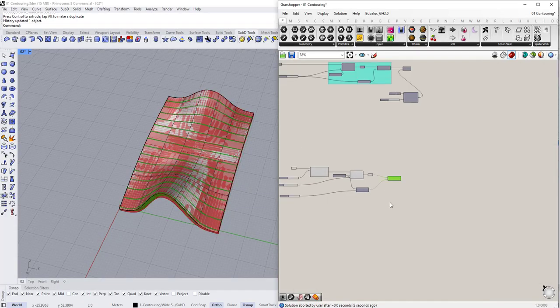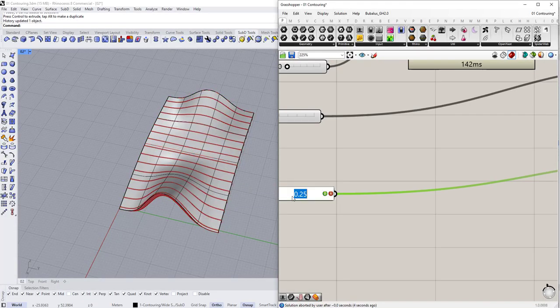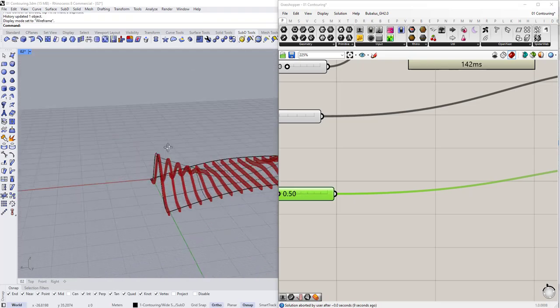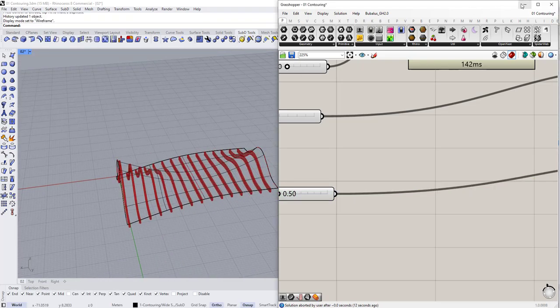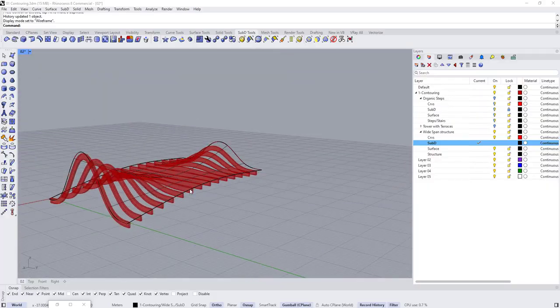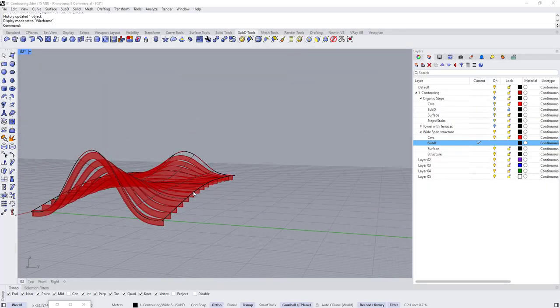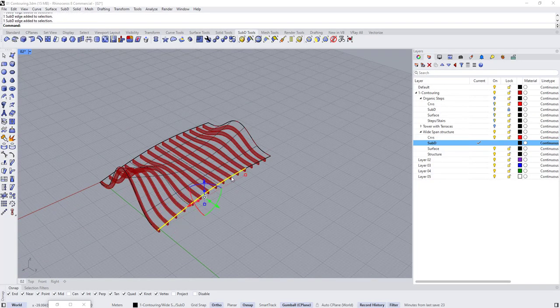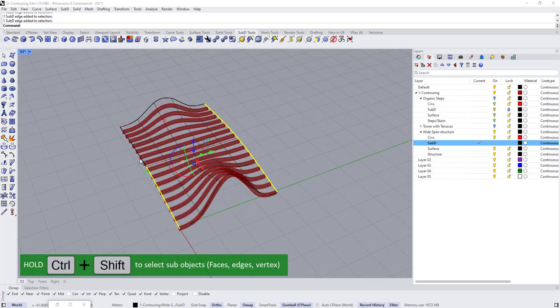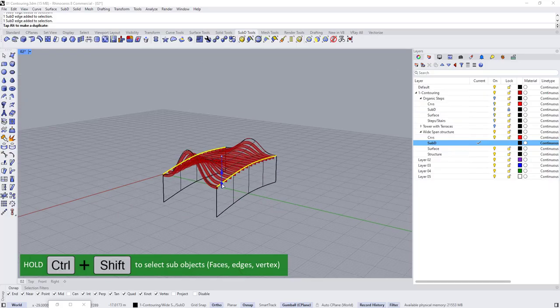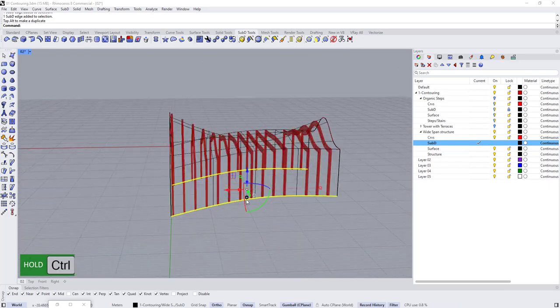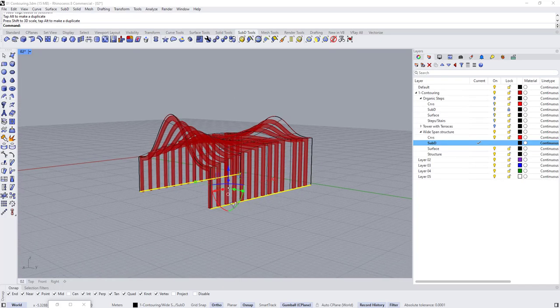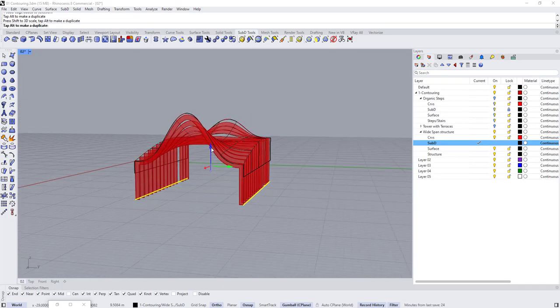So we can hide. So these are like the main frames. Switch to the wireframe. So what we can't have are floating beams. This should be frames. So we can't have floating beams like this. So what I have to do right now is maybe select this edge like this. Control Shift, select all these edges, and let's extrude it. So that's fine. Now let's scale this to 0 to make it horizontal. And here we go. We have our frames.